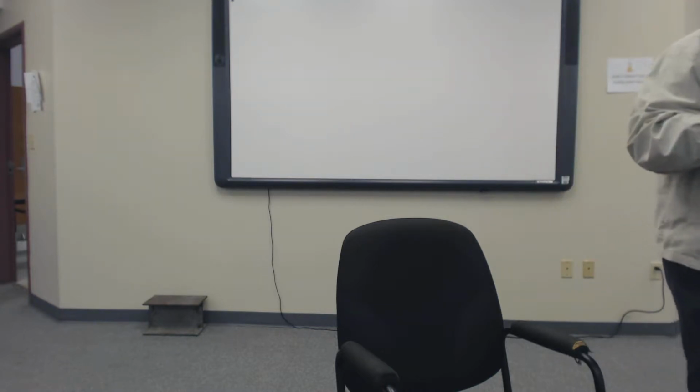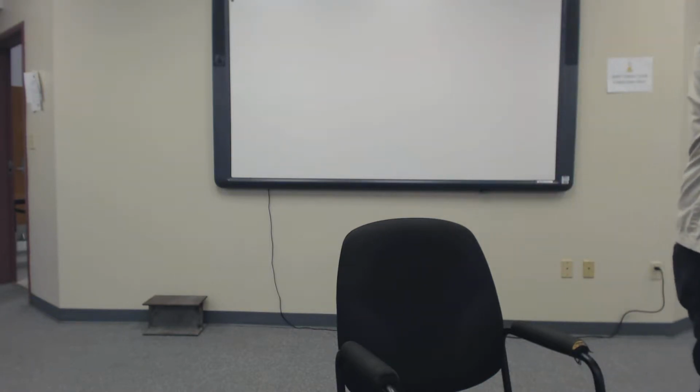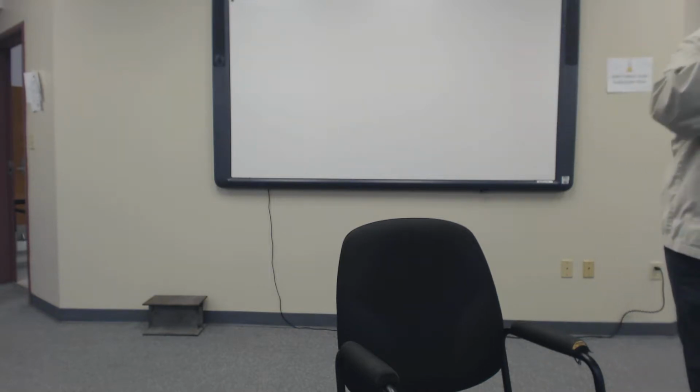I used CMU block all the way around it. And then on the center of the house underneath, I put in a CMU pile, which means I just took CMU and stacked them on top of each other to give it a load-bearing spot right down the middle of the house. Okay, and you'll see it when I pull up canvas here in a minute. So basically, in the crawl space system, I put a pile right down the middle made out of the same CMU to help support what's going to sit on top of it.